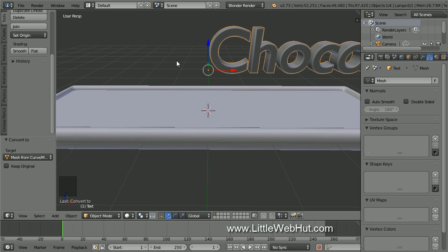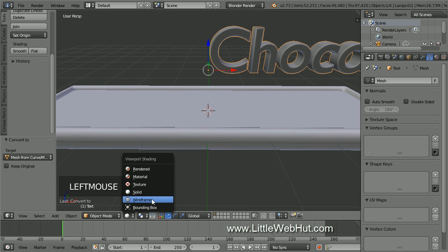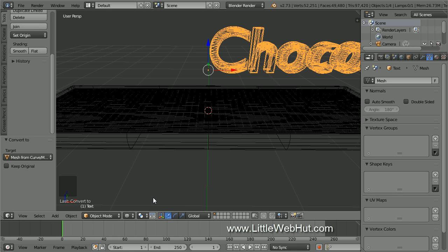During the animation, the text will appear as if it's flowing out of the chocolate bar onto the surface. For this effect, we'll be distorting the shape of the text. So it will help if the mesh that the text is made out of is more uniform. So we'll be using the Remesh modifier because it produces a fairly uniform mesh. To see this, switch to wireframe mode. You'll notice that currently the geometry is not uniform. The curved portions of the text have more geometry than the straight portions.